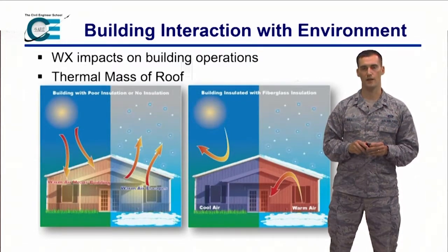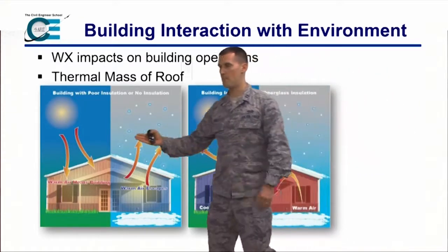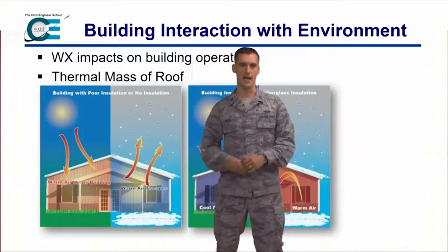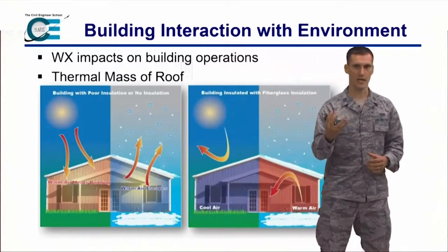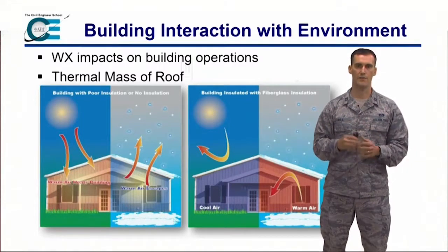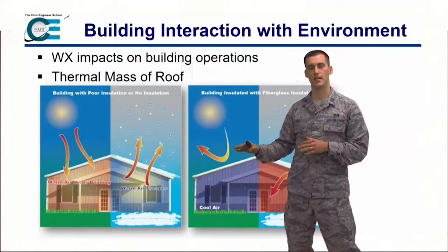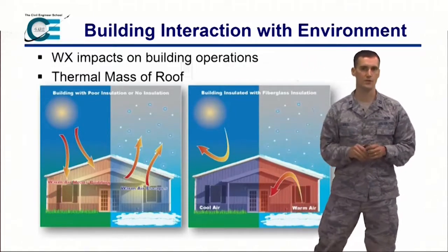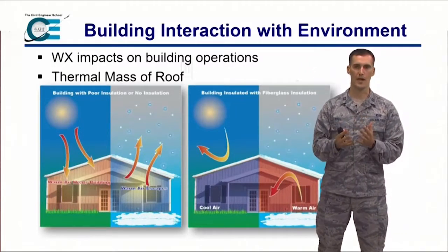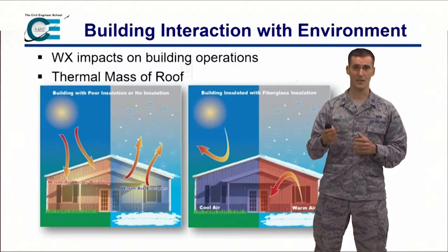In the same way, a facility that is being pounded by the sun during the day, it's going to take a long time for all that concrete to heat up. So that's going to play a factor as well. The point here is that it's not just insulation that affects how much heat transfer we have, but also thermal mass. My house, I've got masonry, I've got brick. That's going to impact it a lot.